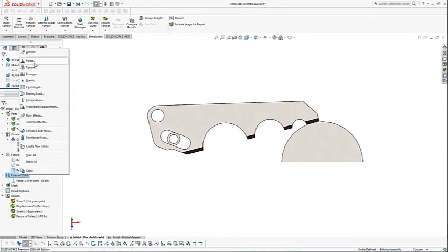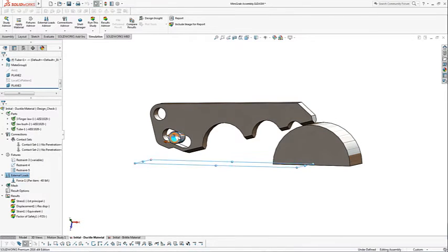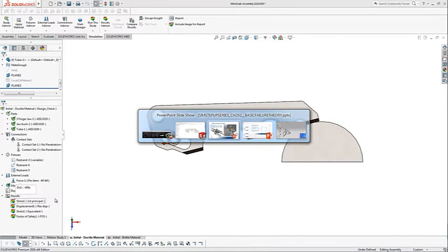And then with respect to force, a very, very simple force is applied, just a force on the interior face of this body. You can see it highlighted there in blue, and it's in the X direction, so moving that thing in the X direction. Now, that's the setup. Let me pop back into the PowerPoint presentation and let's talk a little bit.